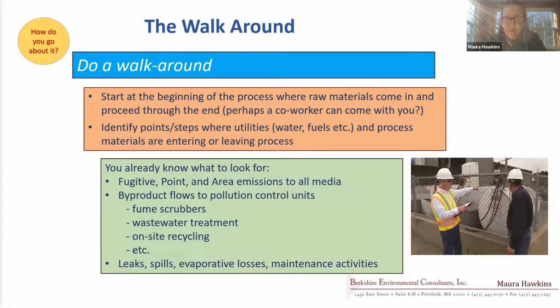The next thing I do is a walk around. I start at the beginning of the process where the raw materials come in and proceed through the end. If you are in your own plant, sometimes it's good to have somebody else come with you, because they might have a different perspective than you have. But certainly I've done it a lot on my own, depending on the plant. Identify all the points and steps where utilities, waters, fuels, etc., chemical storage and process material are entering or leaving